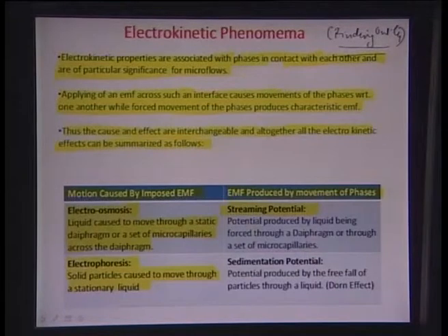It is a potential produced by liquid being forced through a diaphragm or through a set of microcapillaries in the diaphragm. If you are forcing this liquid phase over a solid phase with a diaphragm which has several microcapillaries, it causes a potential because of the flowing fluid. It is also known as the streaming potential.